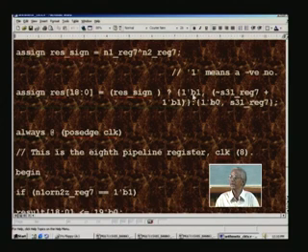That is what is being done here by concatenating the last bit to be the 18th bit, we had to force it to 1, because we know at this stage this number is going to be a negative number. If it is negative this will be 1, this is a mux realization. So naturally the MSB will have to be 1, that is why we force it here. So we need to take the 2's complement in order to get the magnitude.